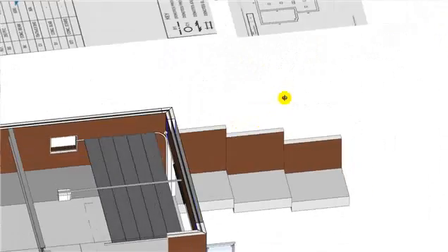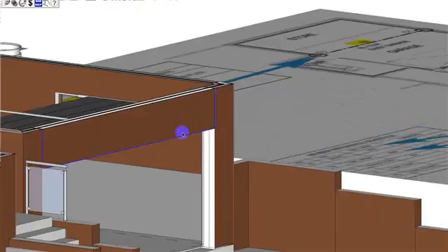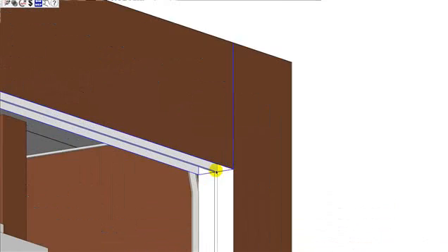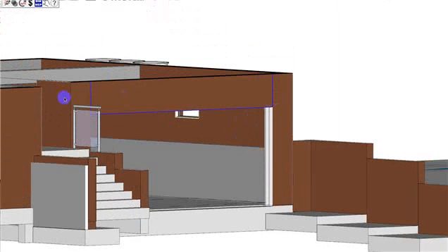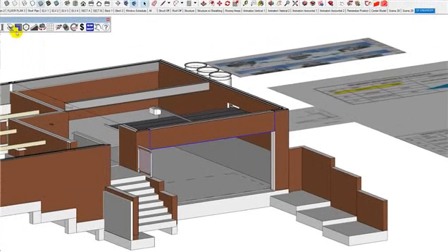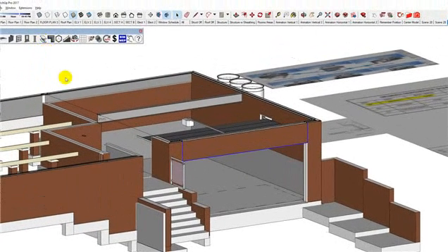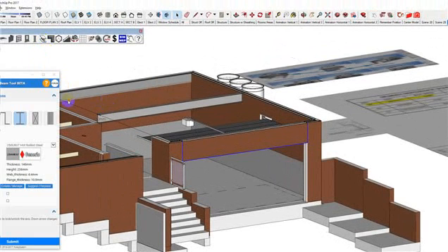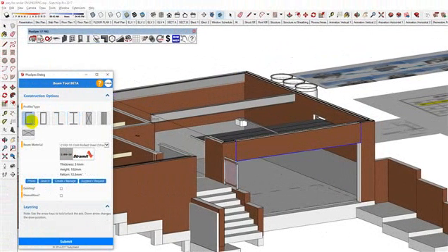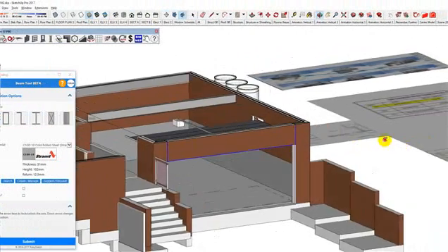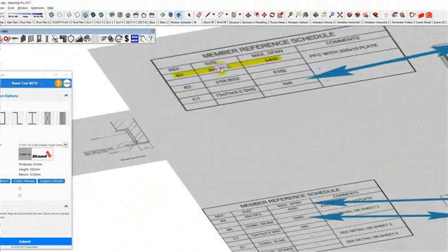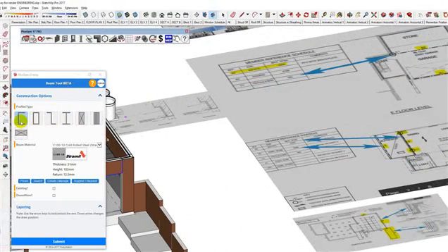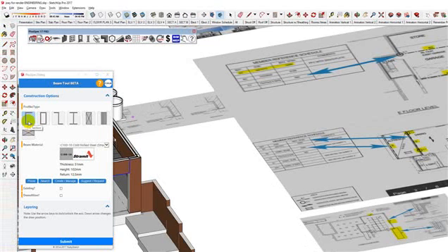What have you got in there now? Okay, there's nothing in there at all. I don't know why you did that. That should have just been one wall and basically a garage door in there regardless. I hope I have a beam in there to do that. Let's have a look. I need to go back and see what type of beam it is. Beam 1 is a 300 PFC. Yeah, it's going to be okay.